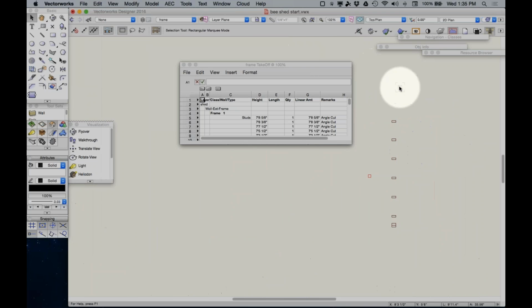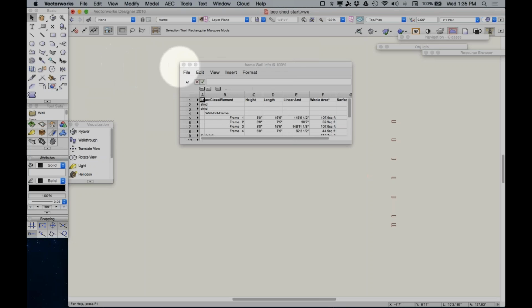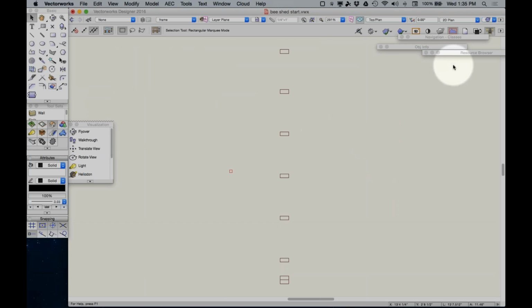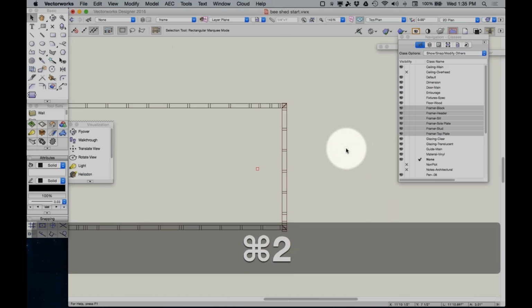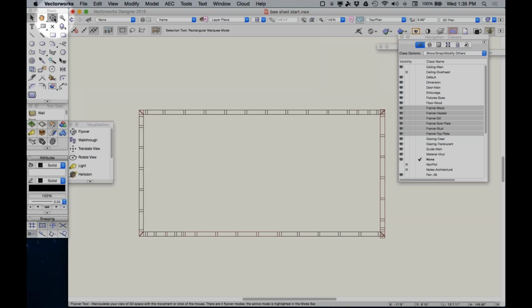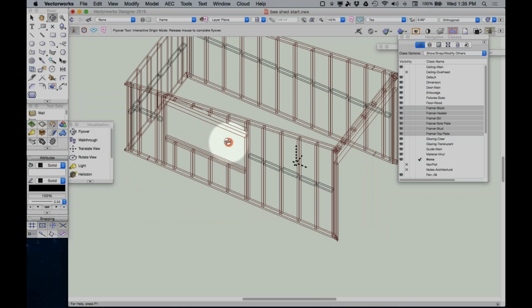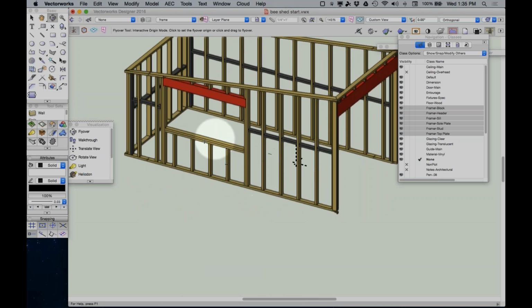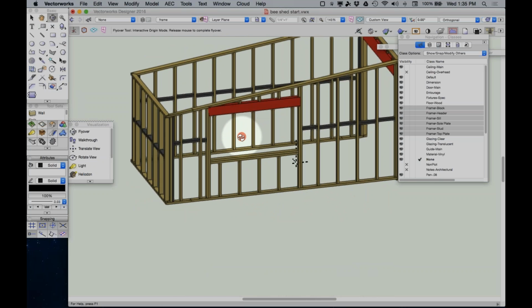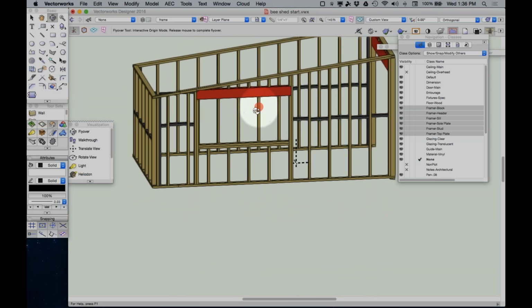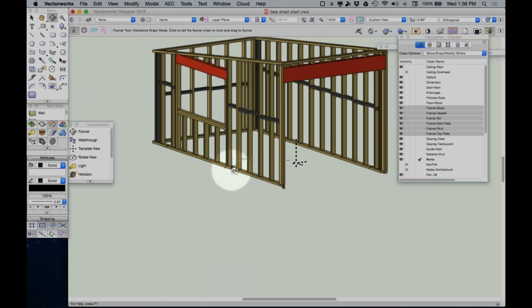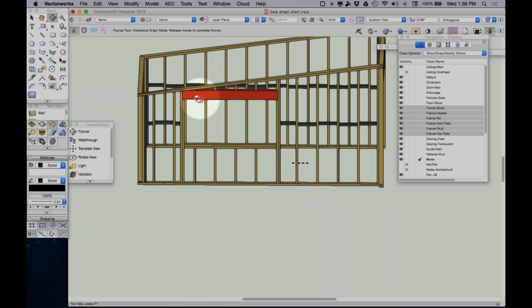And then I've got some new classes that Vectorworks created for me. So here is my framing model, just based on those walls. Vectorworks applied certain rules, and it created a header of a certain size based on the opening of that window or that door. It gave me a single sole plate, a slope top plate, blocking and so forth. Most of those objects are meshes and extrusions.